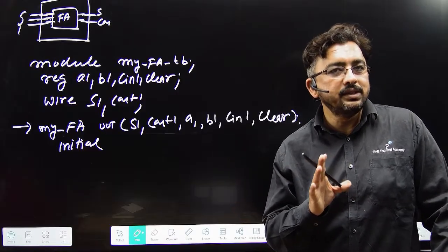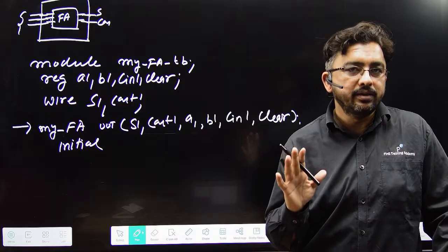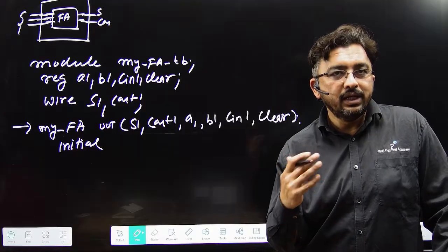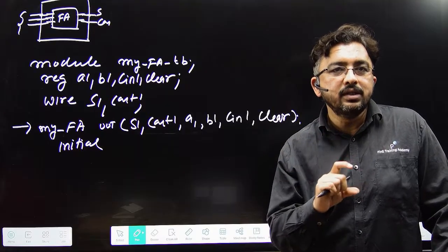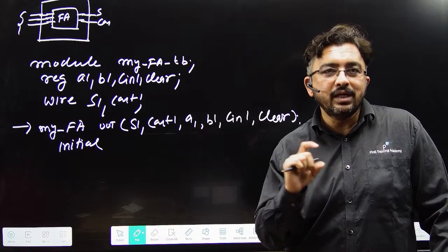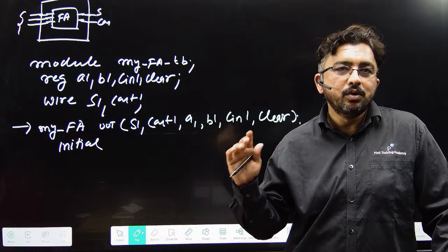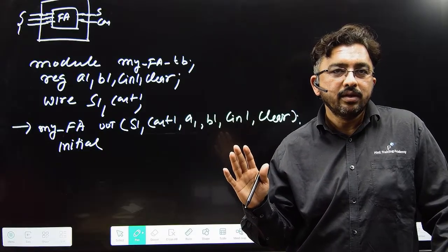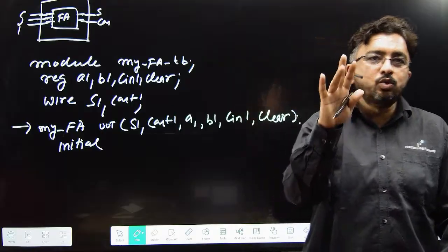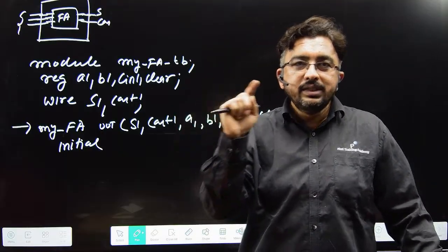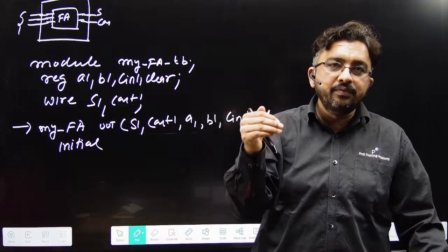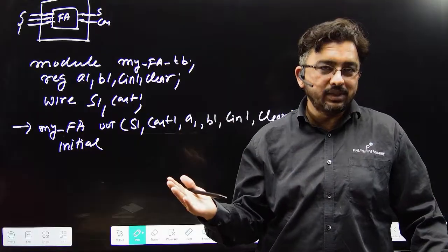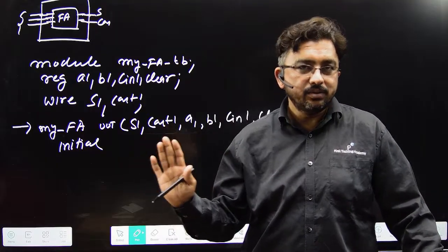Procedure comes under the behavior modeling. After the gate level modeling, there are two things: continuous assignment statement and procedural assignment statement. Procedural blocks come under behavior modeling, and in that there are two blocks: initial and always. Inside the initial, we define the value at 0 nanosecond and it terminates automatically at 1 nanosecond.